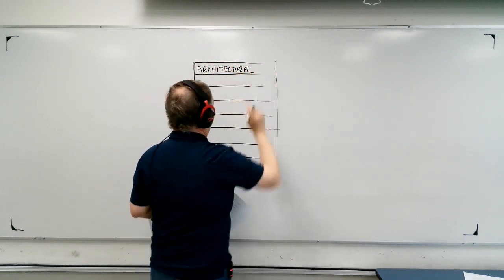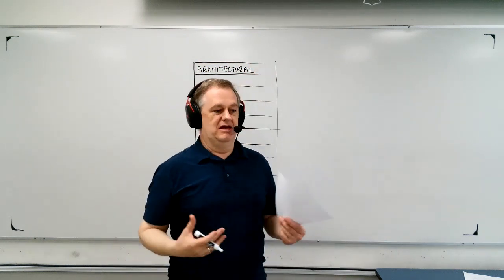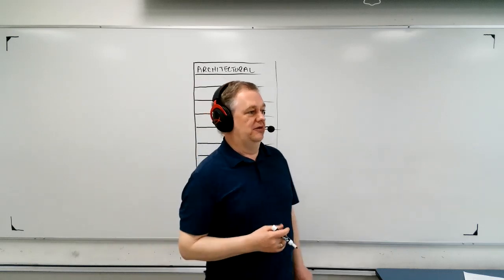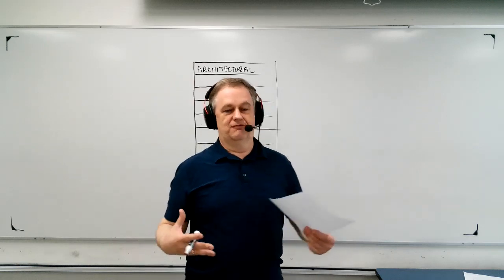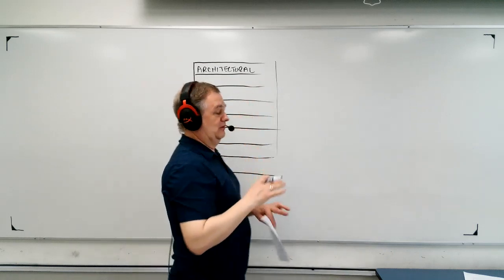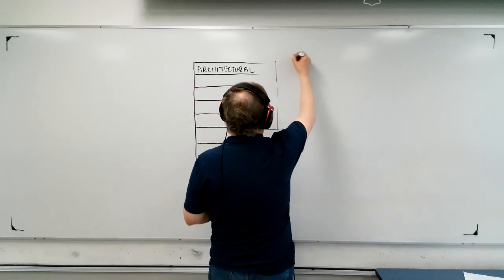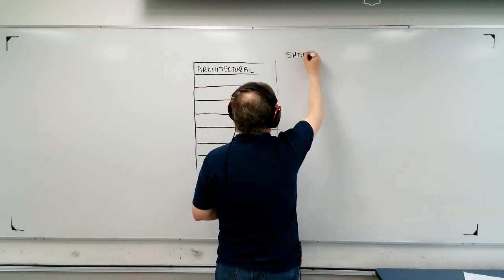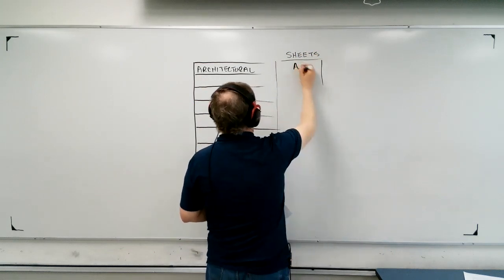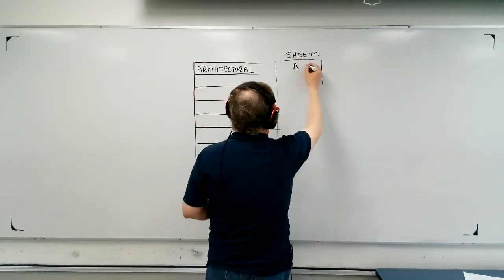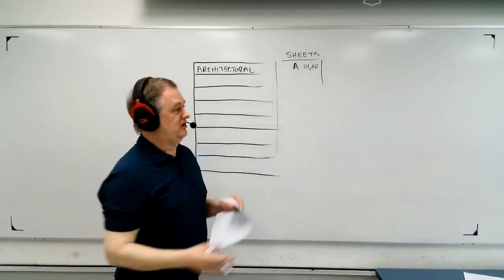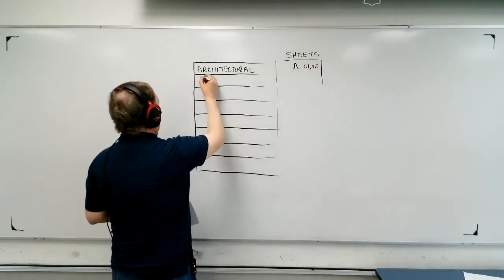Now, these are the drawings that are basically outlining the actual structures, the things that are going to be built in terms of the framework and so on of the whole building. Architectural. Now, these sheets, as we call them, the sheets that are part of the plans, will be lettered A. So it could be A-01, A-02, and so on, to as many architectural sheets as there are. The next one, structural.